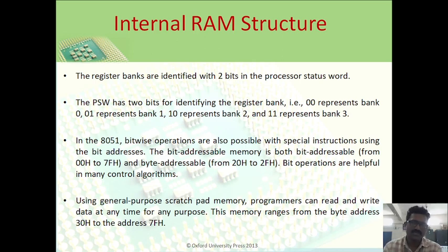For general purpose scratchpad memory, programs can read and write data at any time for any purpose. This memory ranges from the byte address 30H to 7FH. So this is the memory organization and internal RAM structure of the 8051 microcontroller.